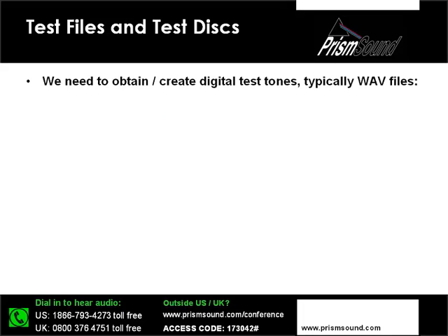So we've already seen that there is a need to create test files. Typically we're dealing with WAV files, so linear PCM format. In other words, uncompressed PCM digital audio that will give us the highest quality signal possible. And that's important because what we don't really want to do when we're measuring these devices is to analyze the performance of the codec. That may be something we want to do independently, but from the point of view of analysing things like the power amplifiers, the signal processors inside our playback device, we want to play a high quality linear PCM file if possible.